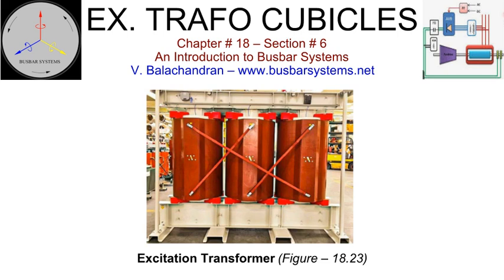The connection inside the excitation transformer to the incoming high voltage terminal of the coil is extremely critical. It should be well insulated and adequately supported. For large-sized generators, it may not be possible to size the cross-section to meet the short time rating of the tap-off bus. The short-circuit forces are likely to be extremely large in the event of a line-to-line or 3-phase fault, and hence the connections must be brazed to withstand the same.